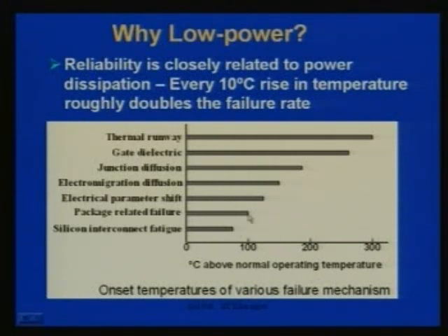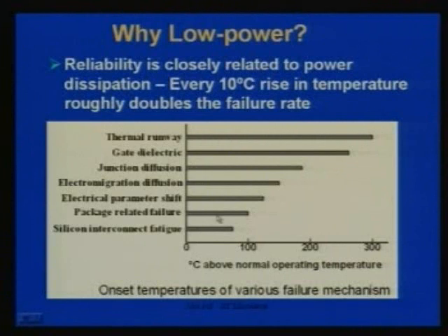If the temperature is 100 degrees above ambient, some of these failure mechanisms will be active, and as a result the chip will fail. So reliability is closely related to the rise in temperature, which in turn is closely related to the power dissipation of the chip. So you have to use low power design techniques so that the power dissipation is small.